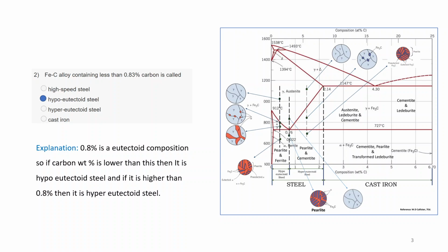All these will be increasing strength, but what is the distinct part? Sulfur and phosphorus are increasing brittleness, and manganese and boron are providing hardenability. You can club those as well: which things are providing hardenability, which thing is providing hot heat resistance, which thing is providing corrosion resistance. For corrosion resistance, basically, those which provide a Pilling-Bedworth ratio between 1 and 2. So nickel, chromium, copper, these three will be the ones providing good corrosion resistance.